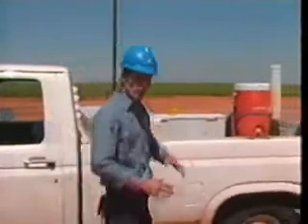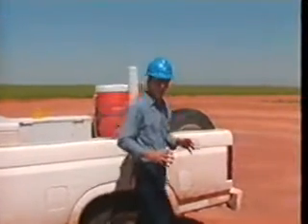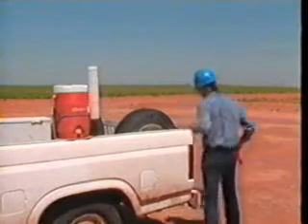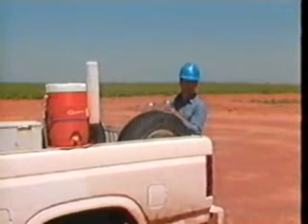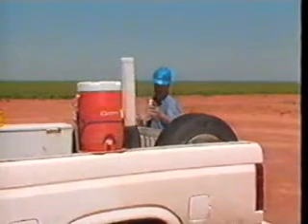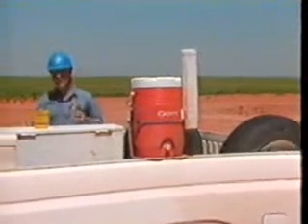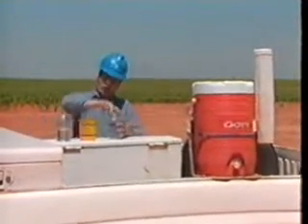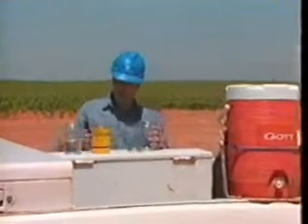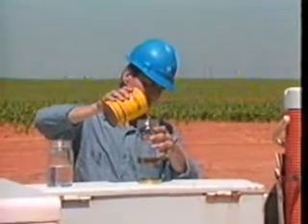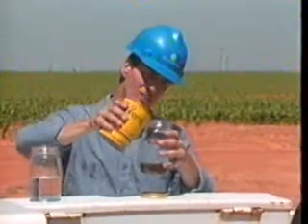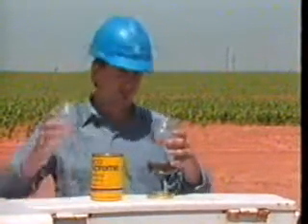The time needed to completely separate an emulsion is called settling time. Now, the settling rate of a water and oil emulsion is affected by viscosity, size of water droplets, and gravity. Now, let me show you what I mean. I'm going to make my own emulsion using water and oil. Pour in the oil. Add a little water.